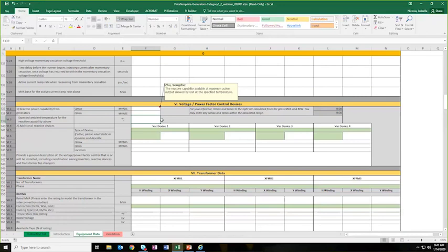Yeah, you're right. On the validation tab, which I'll talk about later, we also check those capability values against the test report. That's why we ask the temperature here. Maybe Qmax, Qmin is at 25 degrees, but the test is performed at 20 degrees or whatever. So there's some engineering judgment there. That's why we use the word consistent instead of saying it has to be the same column, because the conditions will be different and we take into consideration the variations, the temperature.